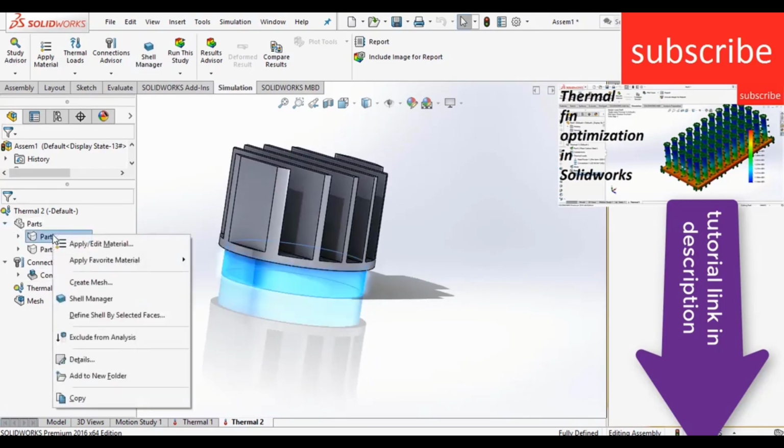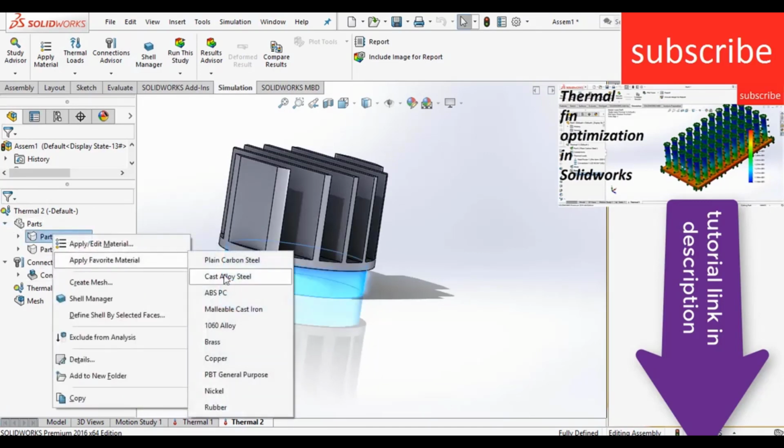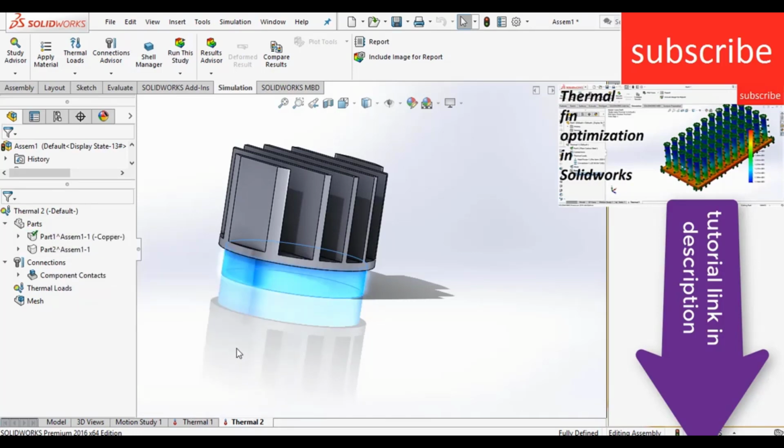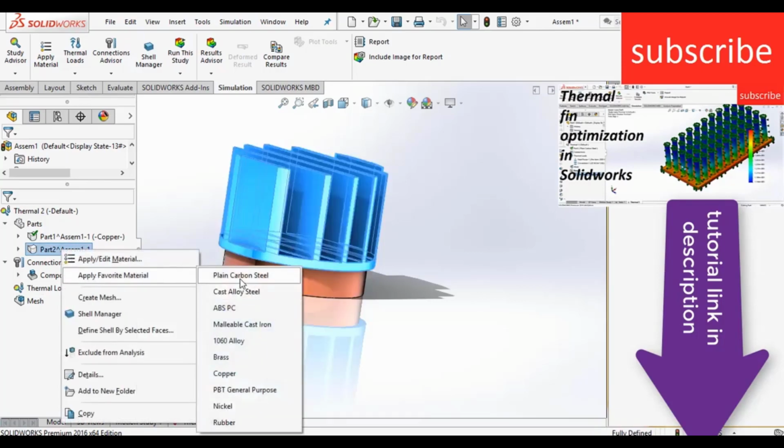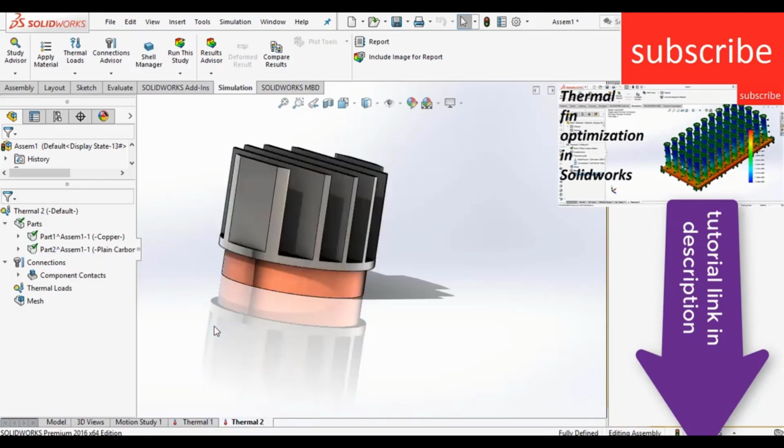So click on parts, right click on part, click on chip material. So basically I am assuming that my chip is made of copper. Remember, you can select the material as per your requirement. Here my main aim is just to show how to give material and how to do simulation correctly. Selecting material and other things is up to you. Okay, and I am assuming that my fin is made of plain carbon steel.